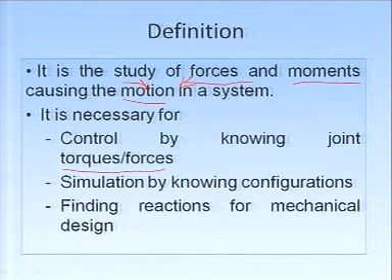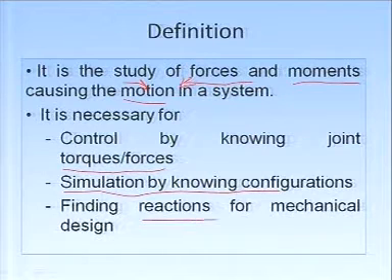Another purpose is simulation, by knowing the configurations. If I give you a robot with certain capabilities of motors and forces to be applied by the motors, you would like to know how it will behave, so you know whether it will satisfy your purpose or not. And thirdly, I would like to know the reaction forces so that I can design. Let us look at my hand and I will describe these three applications of dynamics.